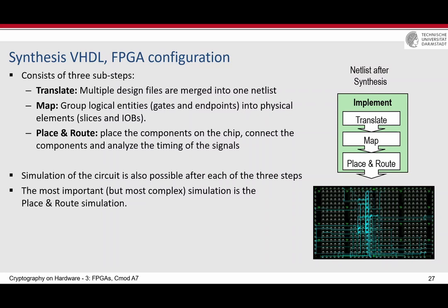And then at the end, you may have a look. Sometimes in FPGA tools like Vivado, you can get a figure showing the CLBs and how they are connected. This is not very informative, but it can tell you that you have a certain line connected from here to here, or that there are long routes in the circuit. Of course, if you click on them and play with the tool, you will understand which net or signal it is, and which gate or LUT or flip-flop it is connected to, and so on.